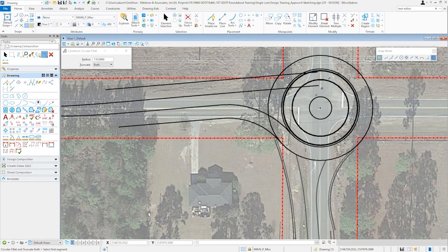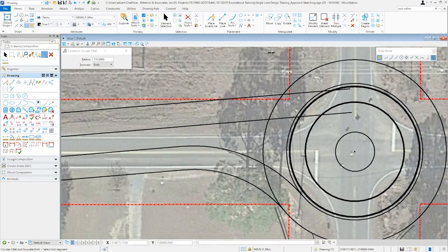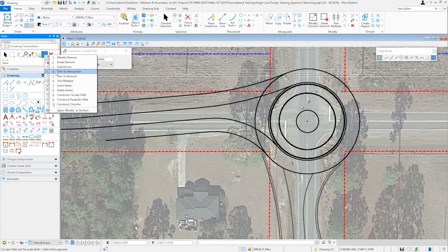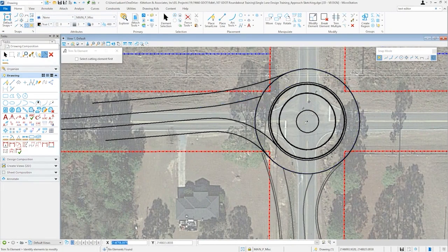And that turns out something like this. You may also recall that we talked about the range of exit radii at the edge of the roundabout being between 150 feet and 500 feet. I like to start with 400-foot radii, so I'll put in 400 on the outside, and then again I add the 20 feet, so I'll tie 420 in there, and that results in entry and exit lanes and the splitter island that looks something like that.